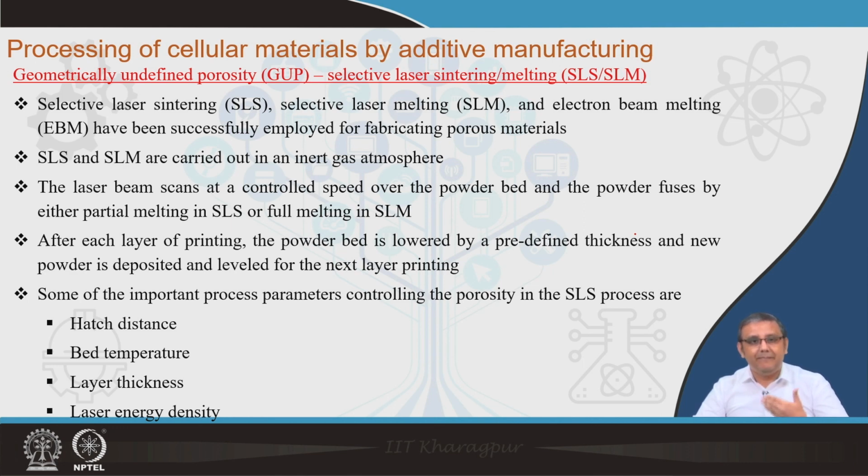Also, there is one important parameter, the laser scan speed. If we increase the laser scan speed, that means for the same amount of laser energy, the energy density or heat input will be reduced, and that will also provide a higher amount of porosity.